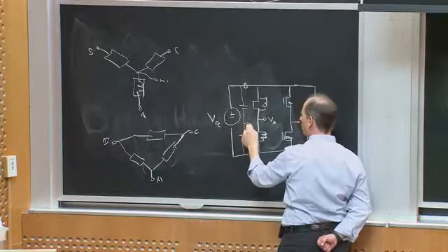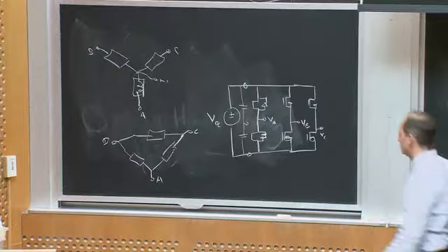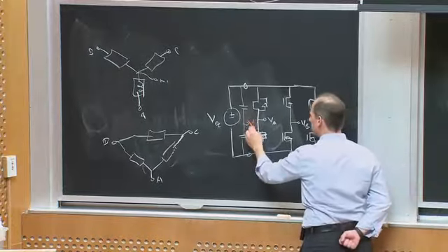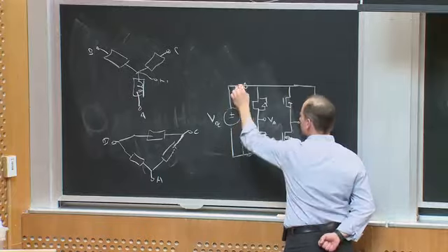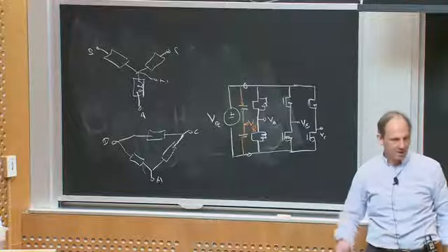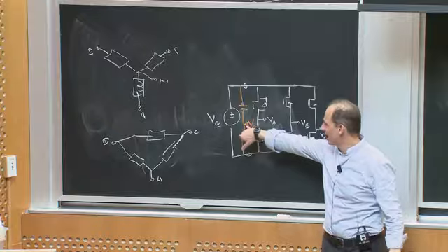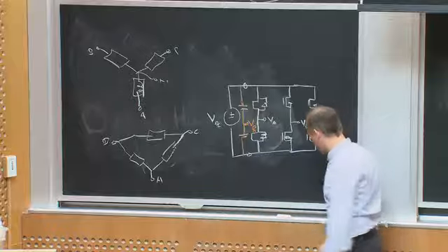Maybe what I'll do is I will consider the midpoint of this bus, for reasons we'll talk about, and I'm going to call this node V sub R. Okay, that's my reference voltage. It's just the center point of the bus. Where I ground this thing, you know, we can discuss that, but let me just pretend that this is exactly in the middle. It's VDC over 2 from here. Okay, and we'll see why we're going to talk about that.